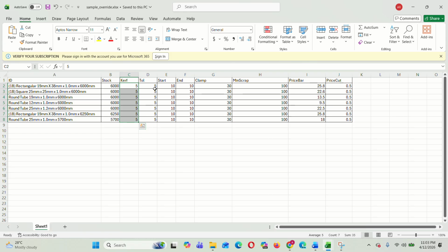With a tolerance of 5 mm, which is plus minus 5 mm, the 995 mm would be considered as 1000 mm, and it would be considered as the second piece of the cut. The reason is that tolerance kicks in and gives a 5 mm additional value to the leftover bar of 995, making it 1000 mm. Technically, in the production environment it would still be a 995 mm piece, but because you have given a 5 mm tolerance, it would be considered as a 1000 mm bar.